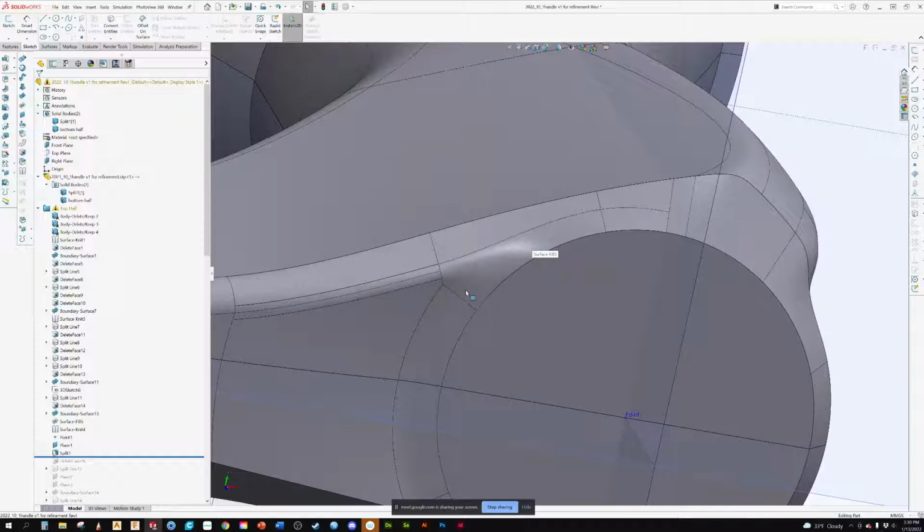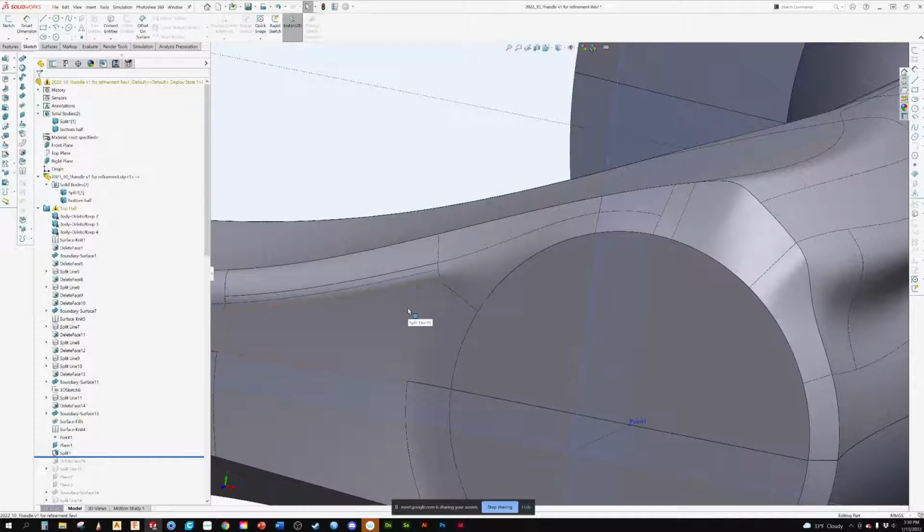So now you can see what happened is I took out what was one surface. I added in 1, 2, 3, 4, 5, 6 surfaces to clean that all up. So it's called patch modeling. I'm not necessarily rebuilding a whole lot of things, but I'm also modeling edge to edge.